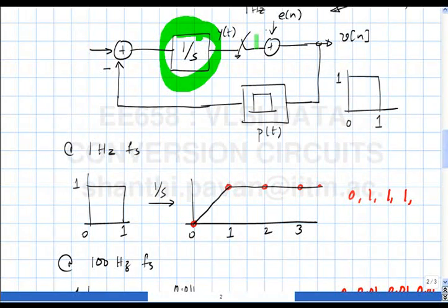So the only other thing in this network which has dimensions of time is basically the gain of the integrator, or the time constant of the integrator. Since you have reduced the pulse width, if you reduce the time constant corresponding to the integrator, all things with dimensions of time have scaled by the same amount, correct?